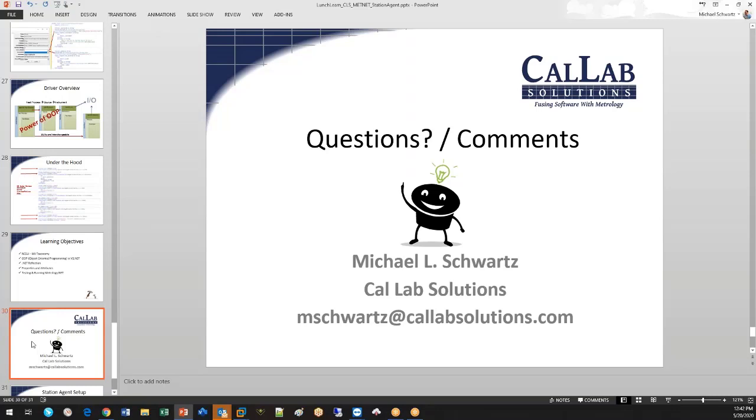Yep. So you can grab your station.config and copy it and then name it. So I'll have like an underscore multifunction calibrator station config.dat. All I have to do is replace my config.dat with that one, and now I'm back up to how it was running. So that's typically how I will do it. The other thing you're able to do is keep multiple directories. So you could keep directory A, directory B, directory C, and then just start it from that directory. It will only scream at you when you try to run two services at a time.